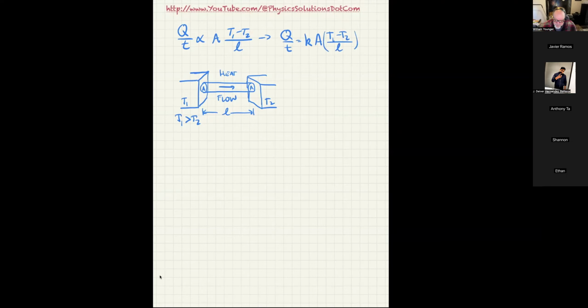So I will say that the quantity L over k is what we know as the R value. If you've ever been on a construction site and seen insulation hanging on the walls, it'll have something like R-19 or R-13 on it. R-13 is sort of the bare minimum a wall can have by code. So you put in R-13, but that R value means L over k.